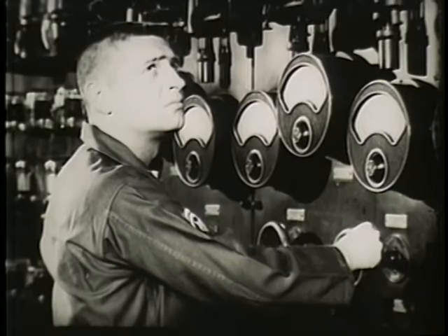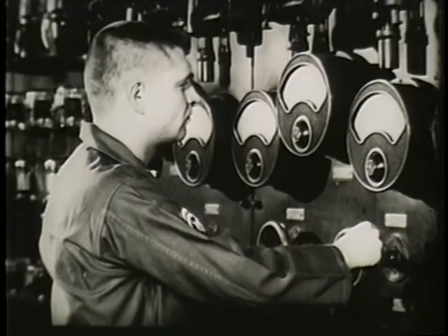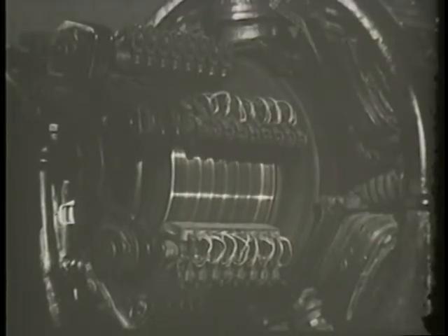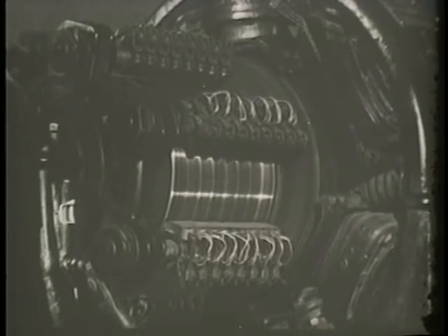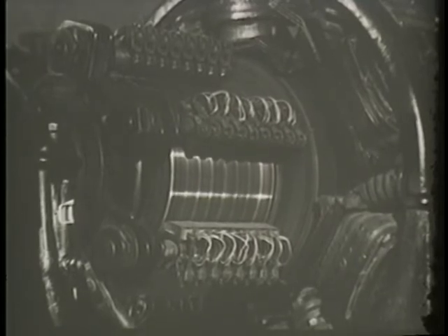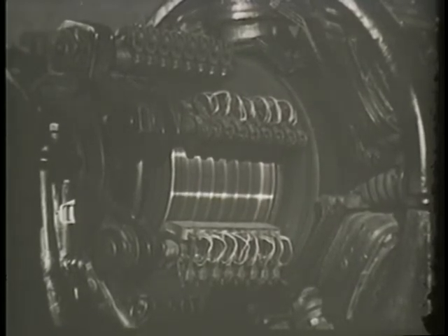When starting large motors, the problem exists of limiting current through the rotor windings until a CEMF can be built up. If the full current is applied before the CEMF develops, it may burn out the rotor windings. Starting boxes are used with DC motors in order to avoid this application of current before the CEMF is built up.